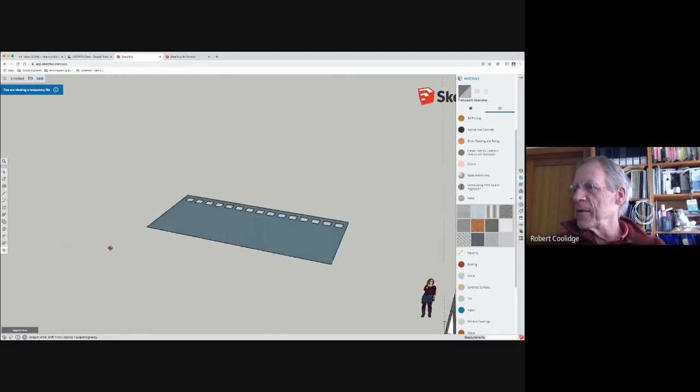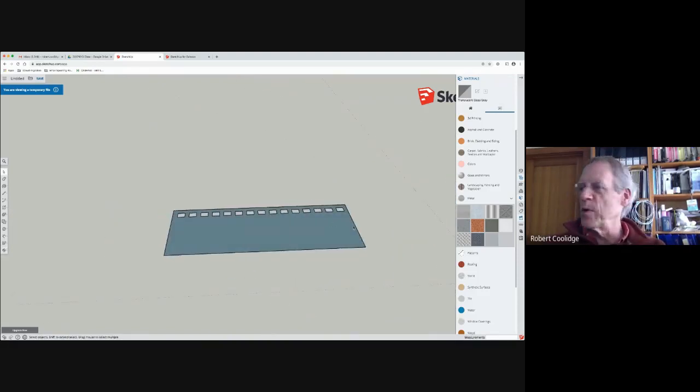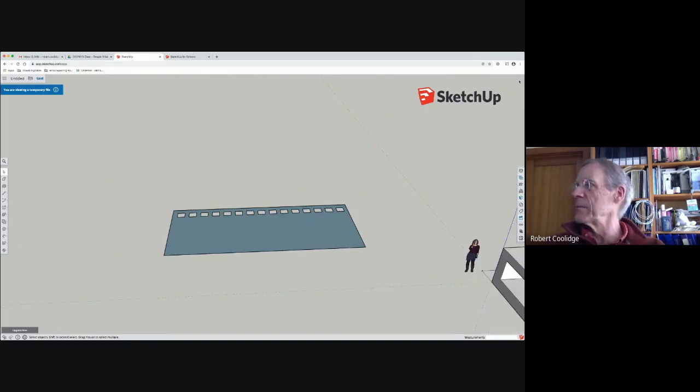I'm sorry that I am struggling somewhat with this version of the program because it's not what I use on a daily basis. I have some typical takeaways for what you need to learn first of all. And as I said, the main one is that everything you do in SketchUp has to be part of a group or component, or it'll drive you crazy.